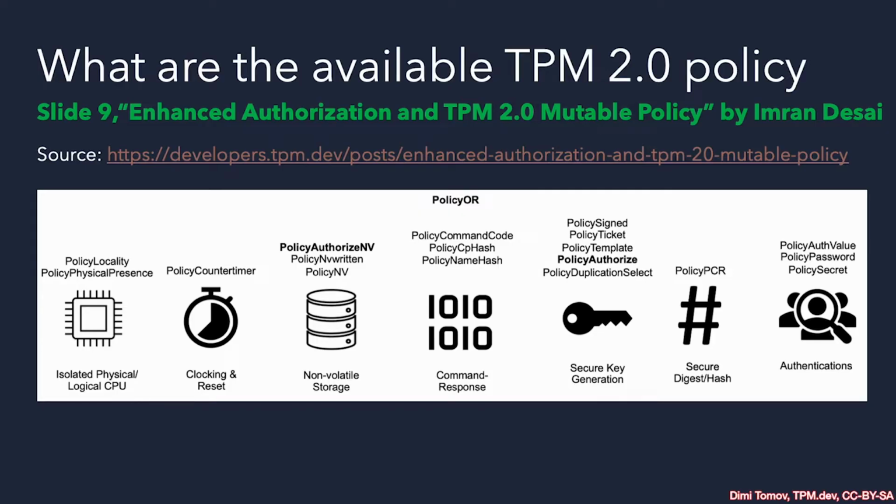Here, I'm using a very nice diagram of the available TPM 2.0 policy commands by Imran Desai from his talk about TPM 2.0 mutable policy. This diagram allows us to see how the different TPM 2.0 policy commands correspond to different properties of the TPM. For example, TPM2 policy counter timer relates to the reset flag, to the counter of the clock, and this way we can create rules that relate to the state of the TPM.